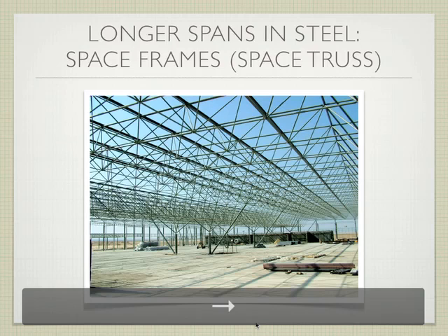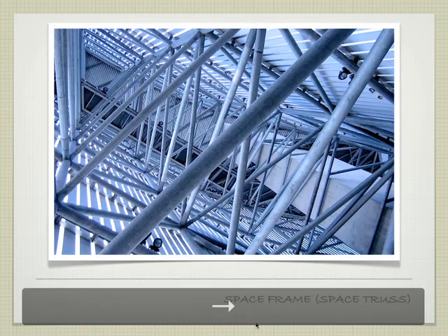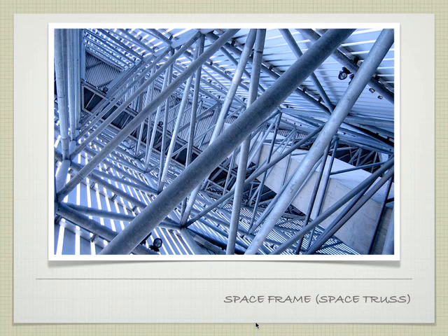So what can we do about it, right? We can have very, very lightweight little elements, and these little elements can span very long distances in both directions because they're all working together as a network, right? Furthermore, we can push the envelope for what they can do, and we can start to transform the shapes. So this is inside a space frame. It has cladding on one side here, cladding on the outside there. This is the section that's providing the primary structure for this particular roof/wall, right?